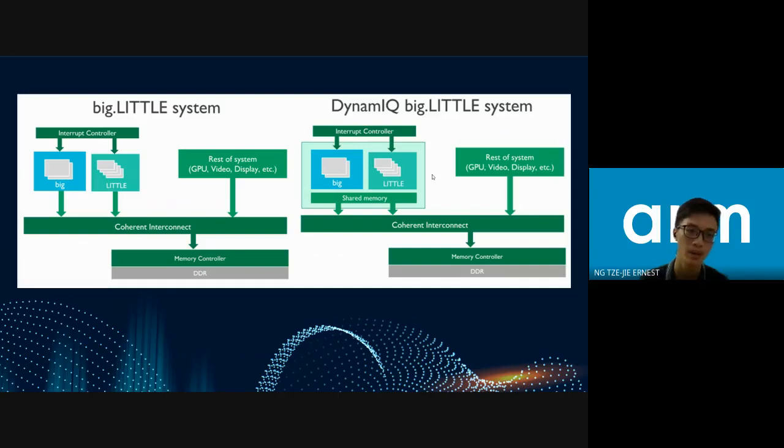same time. While the DynamIQ big.LITTLE is an improvement to big.LITTLE that can support up to 8 big and LITTLE cores in a single cluster, with a DynamIQ shared unit that bridges all cores and cache memories together to ease communication. It can support cores that have different microarchitecture, implementation, cache configurations, and frequencies.